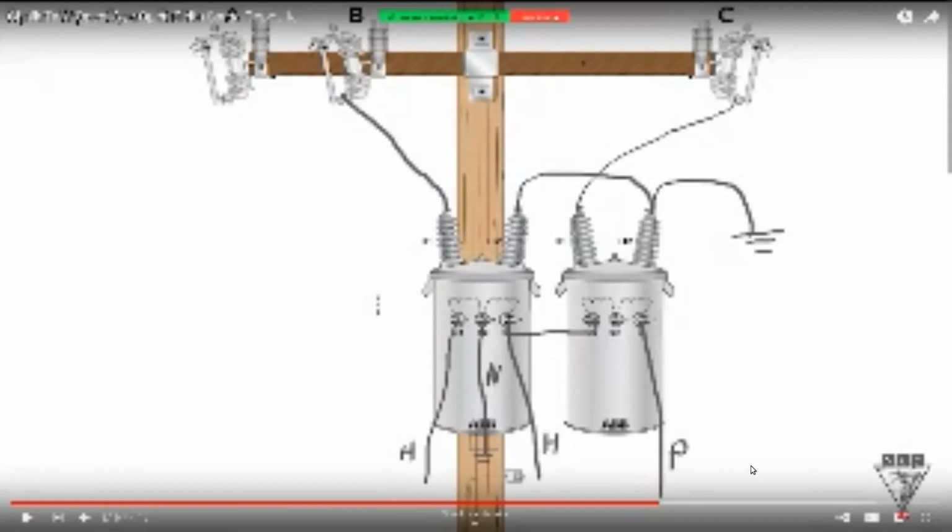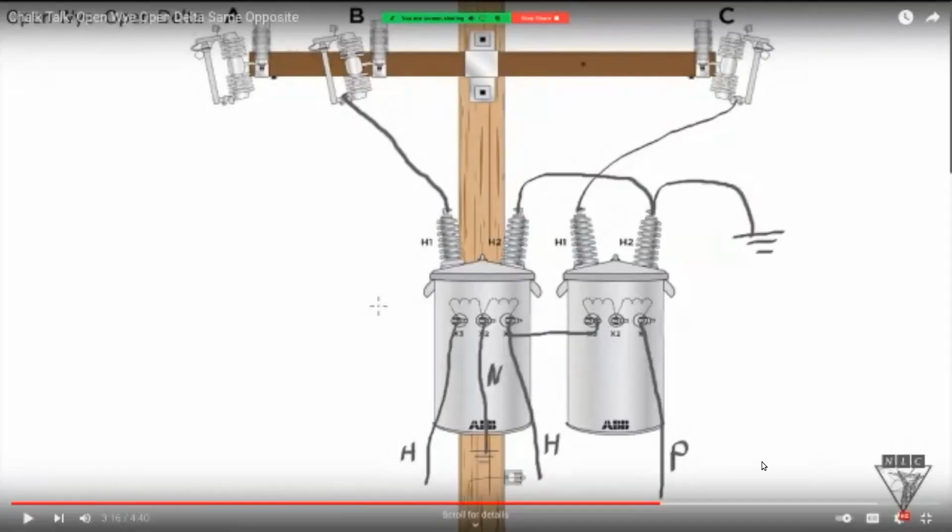But say across the street, I've got a little store that's got some 3-phase air conditioners. I can pull some secondary across the street to them, and I could power those couple of stores or even the one store for 3-phase off the same bank if I use the power leg. So you can use it for multi-purpose right here.